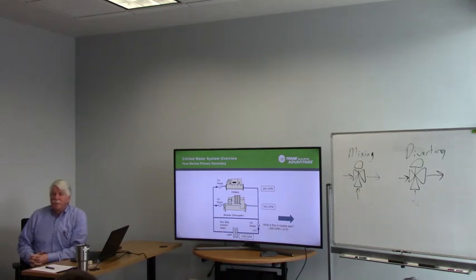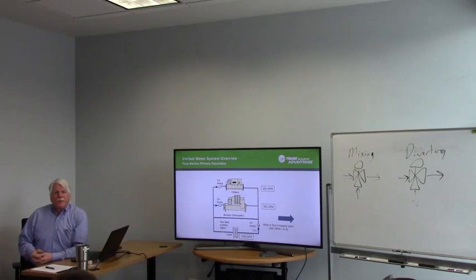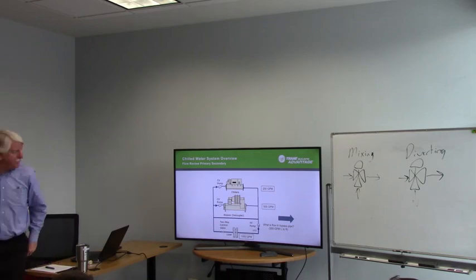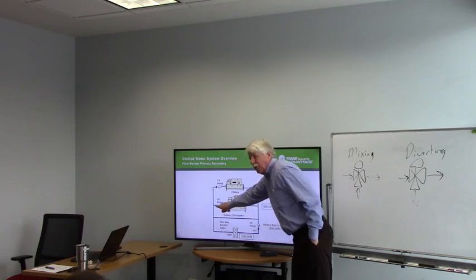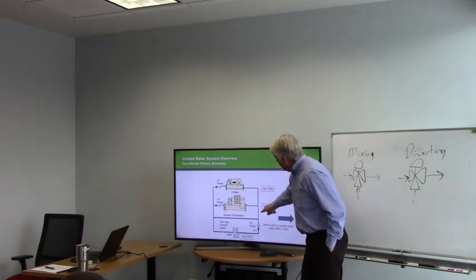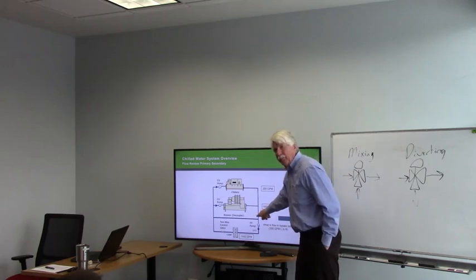Anybody ever seen a pump curve? Yeah, you can see horsepower versus. What kind of efficiency can you expect? Typically, pumps are no more than 60 to 70% efficient. All right? So that means the energy I'm putting into this pump, I'm getting about 70% out of it in flow here.